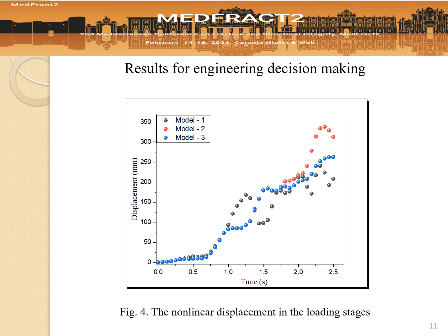Installing geogrid in the best location improves the flexibility of the model, and the embankment collapses with higher displacement, which means allowable displacement has a direct relationship with the location of the geogrid. Higher tensile strength of the model leads to delay in the model collapse. Installing geogrid beneath the toe of the embankment makes subsoil and embankment more stable.